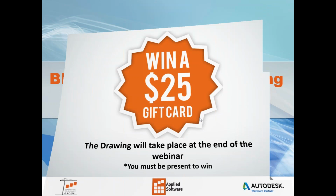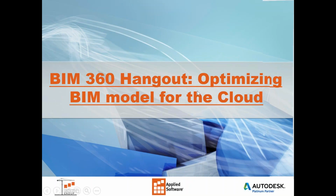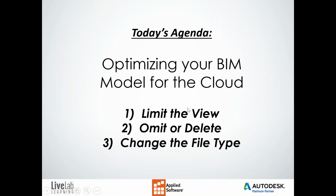Okay, guys. So again, what we're going to go over today is optimizing the BIM model for the cloud. Here's going to be our quick agenda. I'm going to show you guys how to optimize the size of your BIM model three separate ways. One, we're going to limit what we're viewing. Two, we're going to omit or delete items. And three, we're going to look at changing the file type of our BIM models.